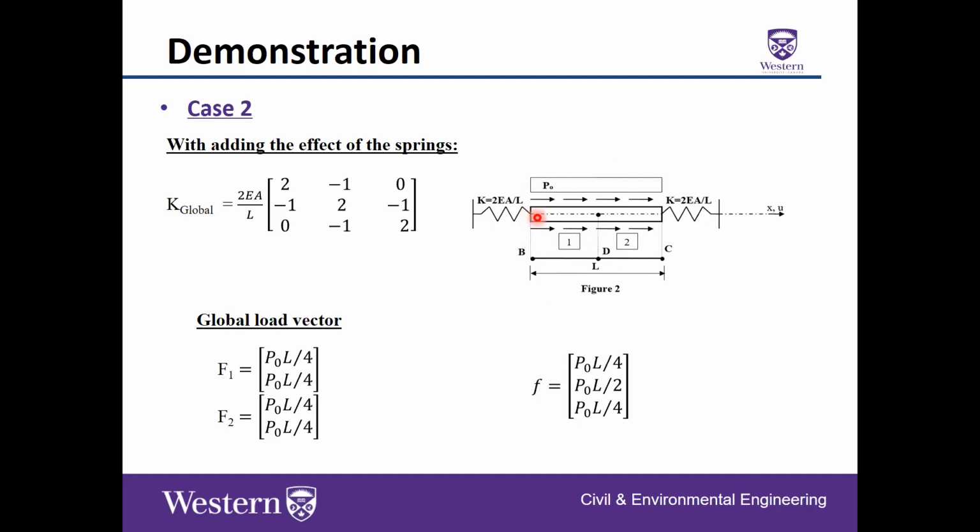That's the logic. If you feel like you cannot just do that, you can go back to the generalized equation for the linearly distributed load, which says that if you have P1 and P2, then two thirds goes to the close joint, and 1/3 of the load goes to the other joint as well, and you will reach the same answer. But just pay attention to LE, which will be L/2 in this case.